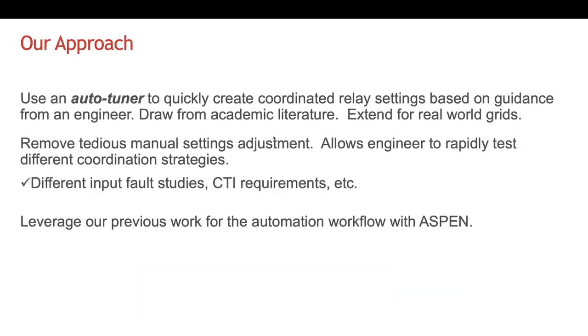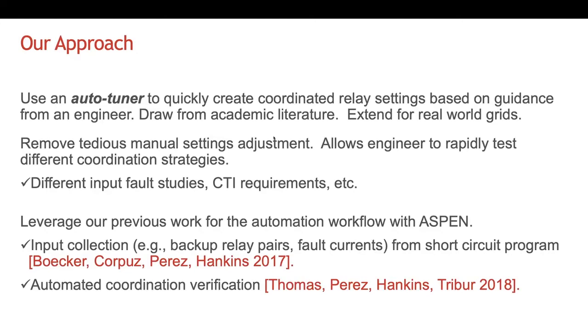So what is our approach? Our approach is to use an auto tuner, which is a term often used in vendors for a given problem. And we will use this to quickly create coordinated relay settings based on guidance from the engineer. I give a few sites in the coming paper, but we draw heavily on the academic research that's been done. I think I went back as far as the 1960s where people were proposing the use of computers to automatically coordinate relay settings.